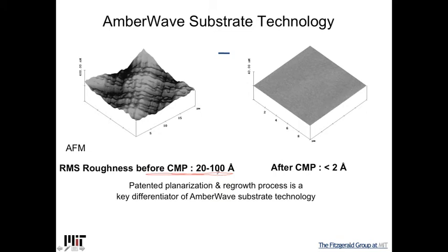And so eventually, because we knew that these things were a residue from previous strain fields, we realized that if we left the top layer a little bit thicker before we put the strain channel on, we could do a chemical mechanical polish. And you can see here that our wafers, when we ended up shipping to the customers, like I said, for years they were wondering how we did this. We'd have less than 2 angstroms roughness.